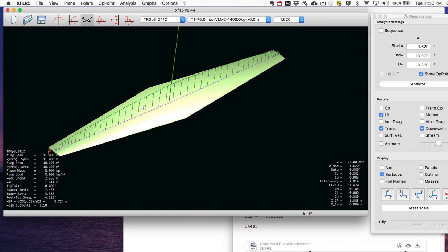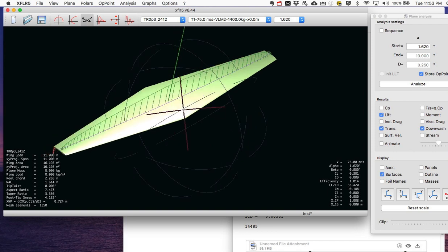So I would recommend using XFoil to kind of hone in on the foils that you think are good. And that way you eliminate one design variable so that you're not trying foils with all different taper ratios, aspect ratios, and twists. You can say, okay, these are the foils that are working well. Now let's play with planforms in order to get the induced drag down, and then kind of combine the two after that. That's just a suggestion. Certainly there are other approaches to this design problem, but that's just a suggestion to sort of take advantage of knowing that those drag components are kind of tied to two different phenomena.